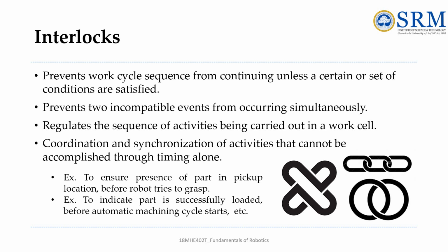Next, coming to interlocks. Let's see what interlocks are. Interlocks in a robot work cell work as a sensor for permitting the work cycle sequence to continue only after the preferred conditions are satisfied. It can be used to perform the following significant functions in a robot cell.